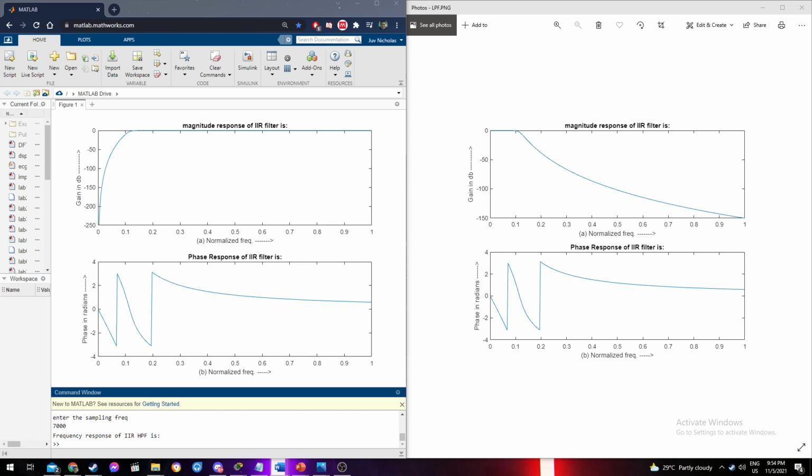The ability of IIR filters to remember previous outputs is both a blessing and a drawback. Perturbations at the IIR filter input, like all feedback systems, can cause the filter output to become unstable and oscillate endlessly depending on the design.